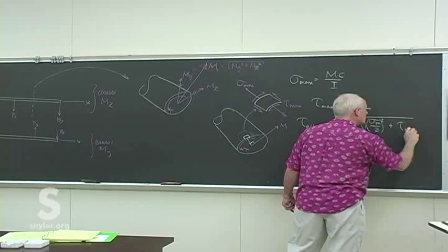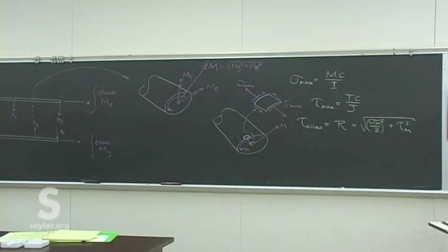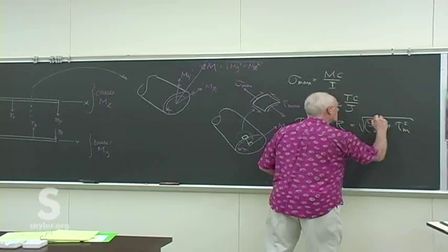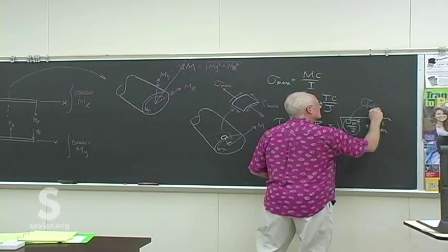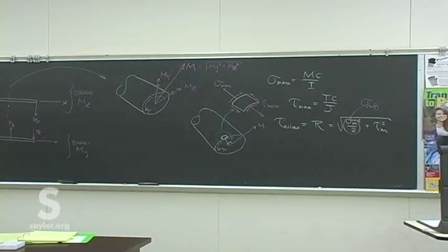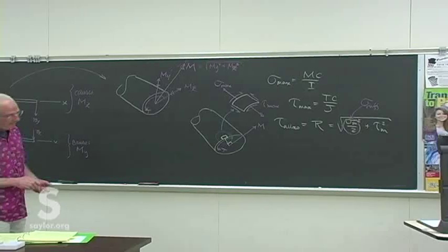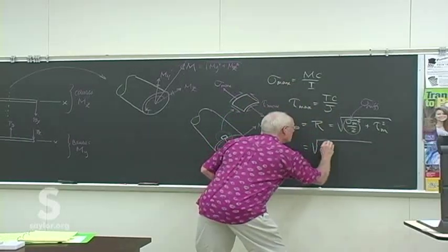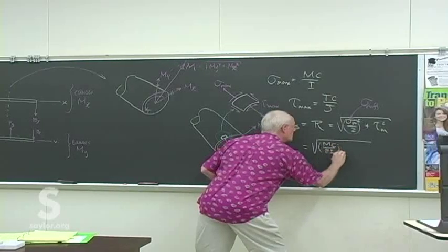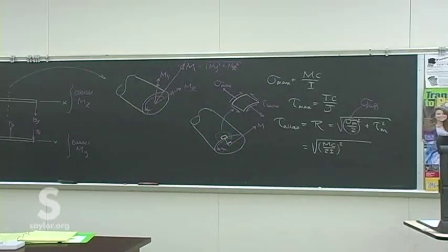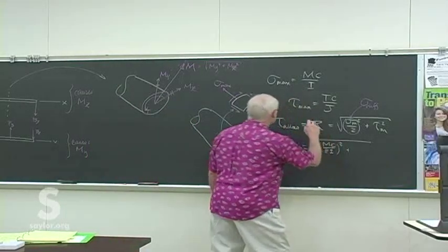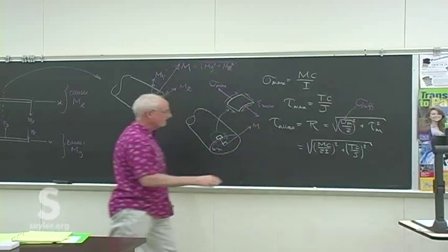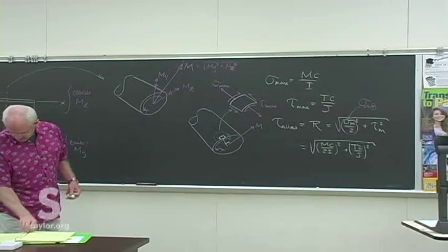I'm just condensing the picture a little bit. And we did that for Mohr circle a bit ago, where this is that thing I invented, tried to patent, couldn't do it, called sigma diff. All right, and we've got those pieces up here. So this is going to be MC over 2I. That 2 on the bottom is from the sigma diff over 2 that we had for the radius, and the TC over J, also quantity squared. And so we relate that to the allowable shear stress.